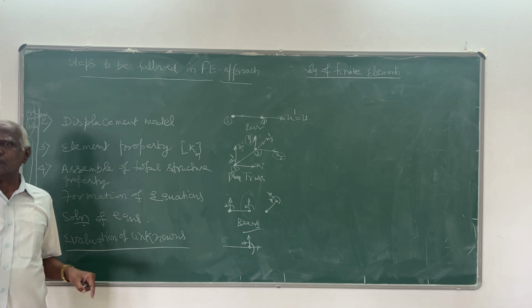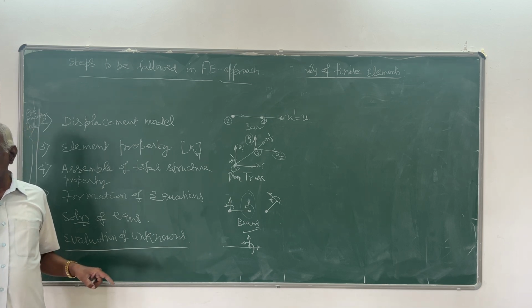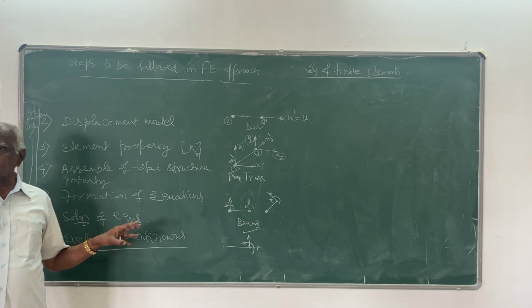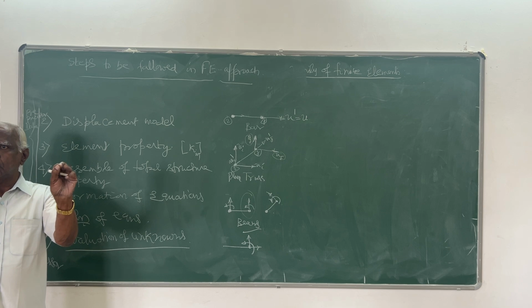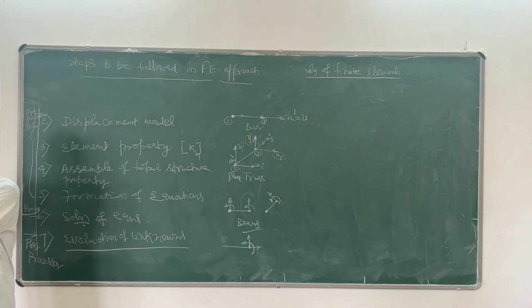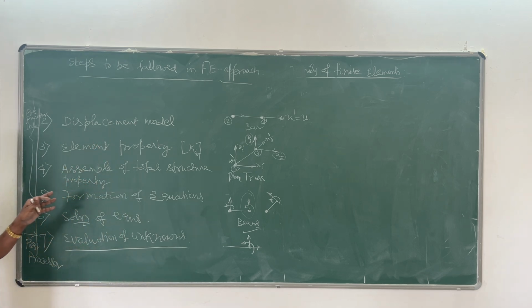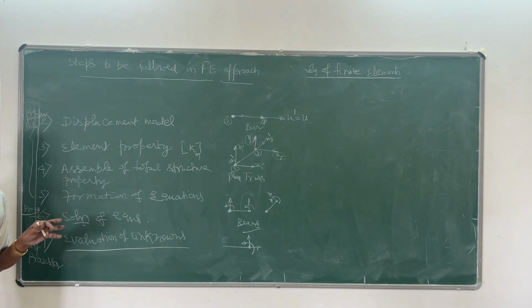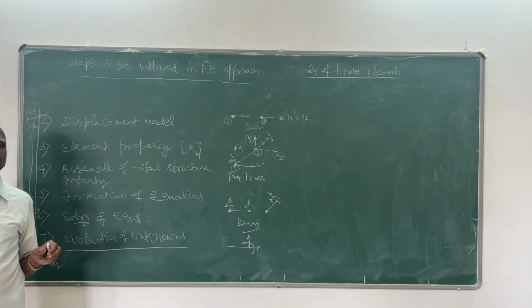Afterwards, you will impose the boundary conditions, right? First, by formulating the equation, you don't impose any boundary condition. You will assume each end to be free. It has to follow rigid body motion. That I will set out as the criteria. Each body has to be capable of undergoing rigid body motion mode. That means it has to bodily move. There should not be any contraction or elongation within the body.